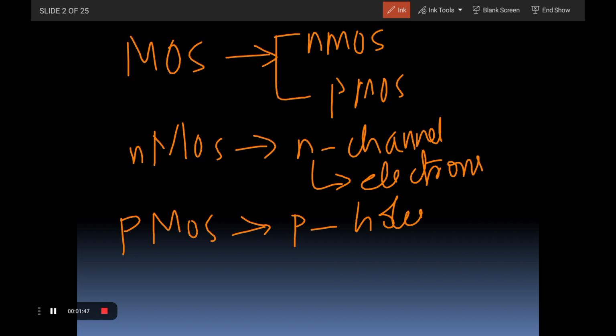Okay, so why it is very important: so this is a representation, right? It is a source terminal, and it is a drain terminal. In between the source and drain we don't have any channel initially. In case of the enhancement MOSFET, enhancement means that initially the transistor does not have any kind of channel. So channel is obviously the gap from source to drain. If you fill that gap with some charge carriers, that is generally called a bridge. We can also call it a channel.